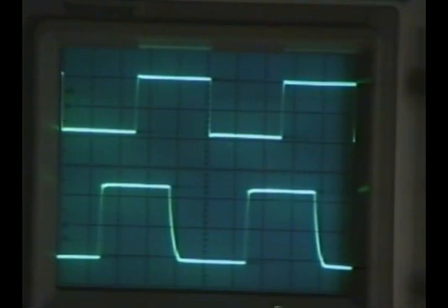And a couple of things we can see. This is 100 kilohertz. This is very close to the free running frequency. Okay, and so what's the phase shift between these two signals right now? Just approximately. I mean, I don't want an exact number. It's about 90, and so guess what? It turns out this phase detector is exactly like the phase detector I described in the notes, which is to say that it operates symmetrically around 90. In other words, it operates from 0 to 180.